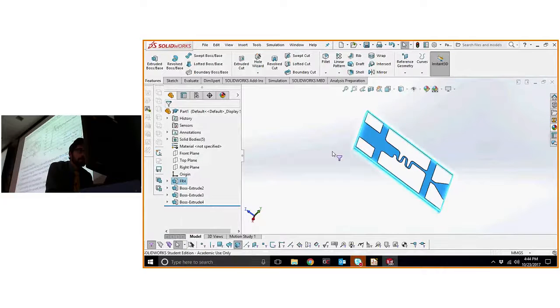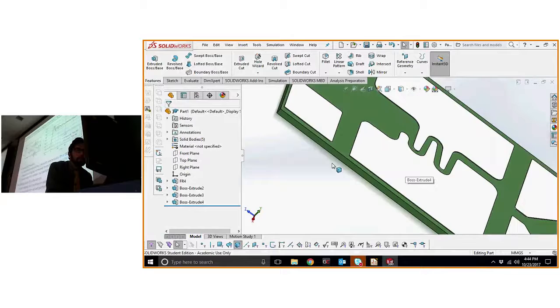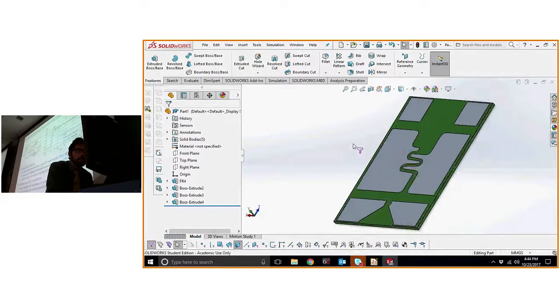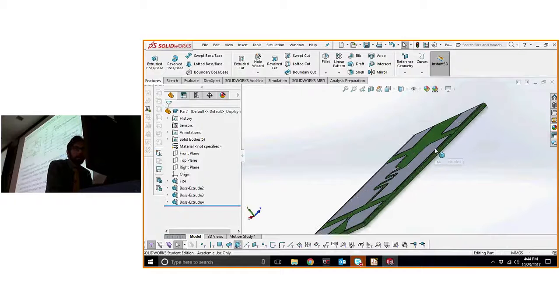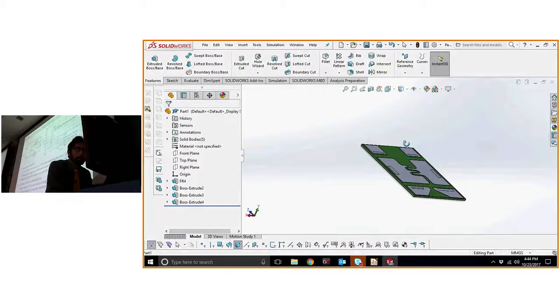And now I can show the FR4. So here's this nice PCB with connections through the layers. I'm not going to do inner layers on this one, but one thing I will point out now, and maybe you've noticed if you're already familiar with FEA, is that the volume of the FR4 overlaps with the volume of those vias, and that will pose a problem in ANSYS.